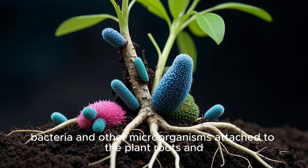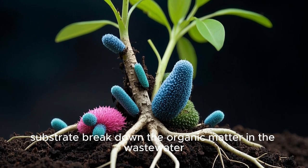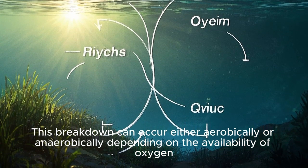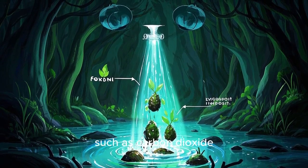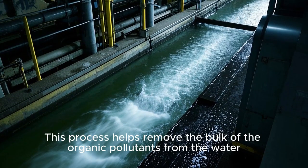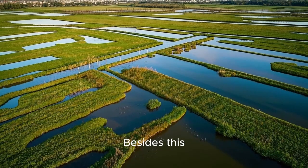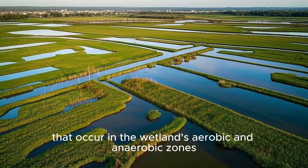One of these processes is microbial degradation. In this process, bacteria and other microorganisms attached to the plant roots and substrate break down the organic matter in the wastewater. This breakdown can occur either aerobically or anaerobically depending on the availability of oxygen. Ultimately, the organic matter is converted into less harmful substances such as carbon dioxide, water, and biomass. This process helps remove the bulk of the organic pollutants from the water, including those in the form of BOD and COD.